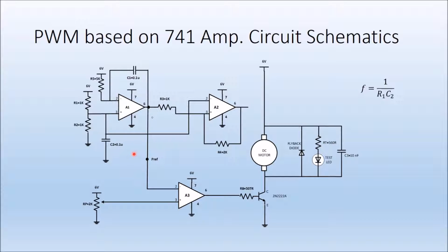The frequency of the pulse width modulation is given by this resistance, or this one, which are the same, and this capacitor. It's a very simple connection, and this here generates an integration phase, and this is an amplification phase. As a result of this feedback here, we generate a triangular wave. So the frequency of the pulse width modulation is given by this expression.